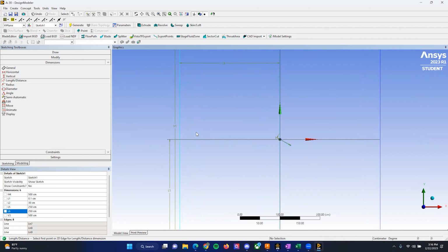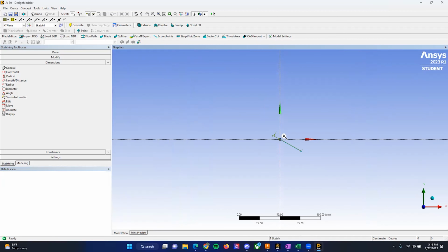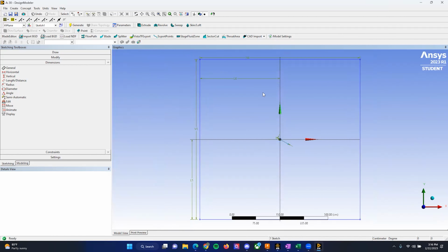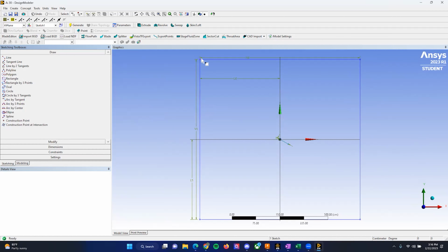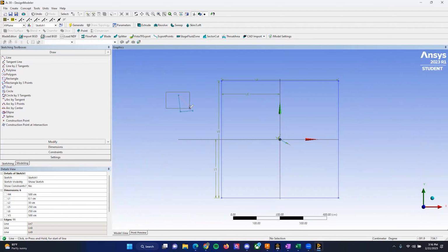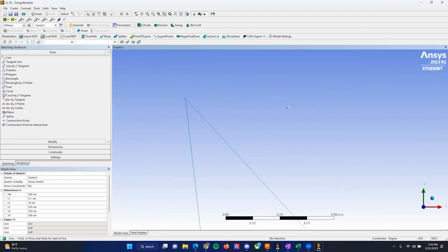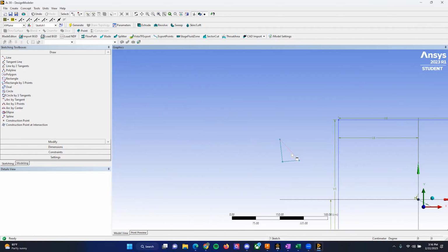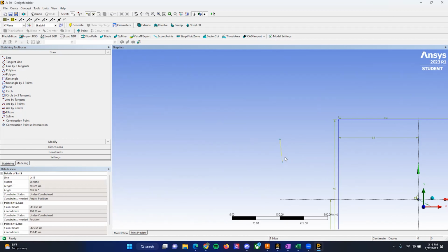So here we have this right here. Zoom in, we can see our plate right here. Zoom out, see our enclosure. Everything's a dark blue. Since we used the rectangle tool, everything should be aligned. Sometimes when you use lines and try to make shapes with lines, and you try to connect vertices, it may look like it's connected, but it may not actually connect, because when you zoom in, sometimes it doesn't actually connect, and it can cause you issues going through each and every vertex.